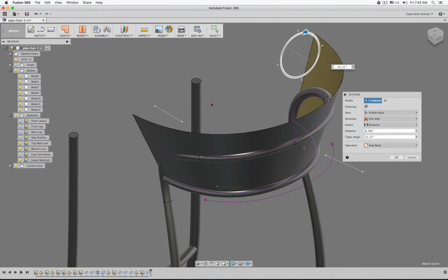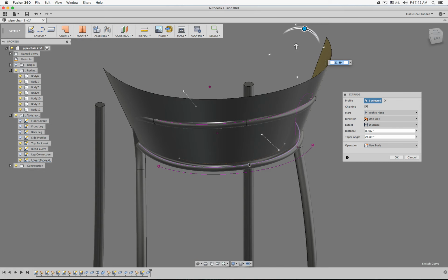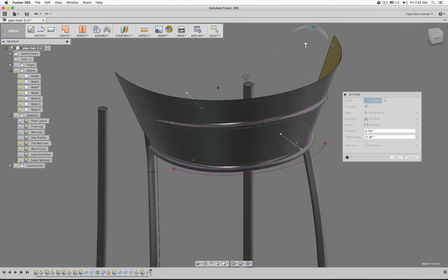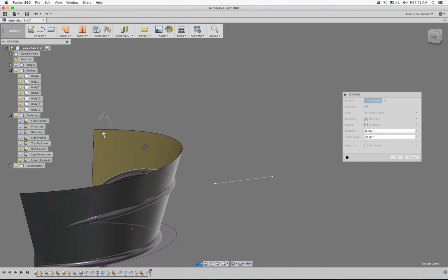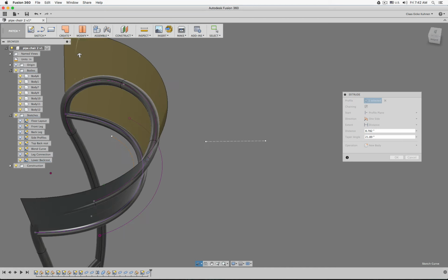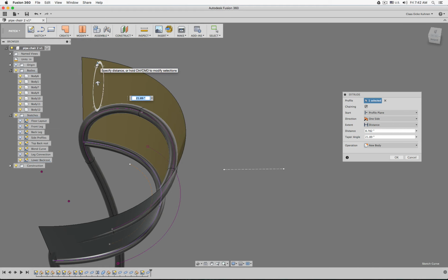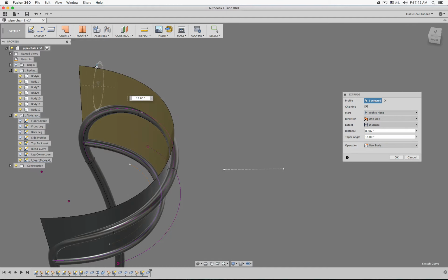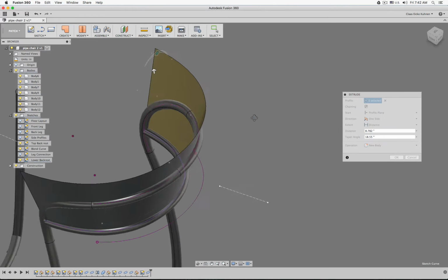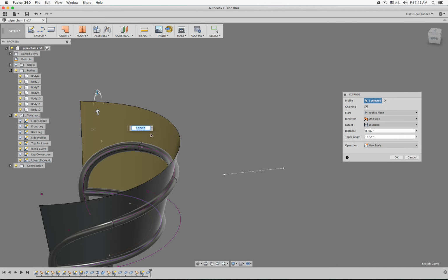And I try to taper it so that, for example, I extrude from this profile and the surface will start matching this upper profile there. The main reason for that is when I offset my surface later, then I can get the surface right in front of my pipes. Okay, maybe I can do a little bit of adjustment by hand, numerically 20, and there. Let's maybe say it this way. Good.